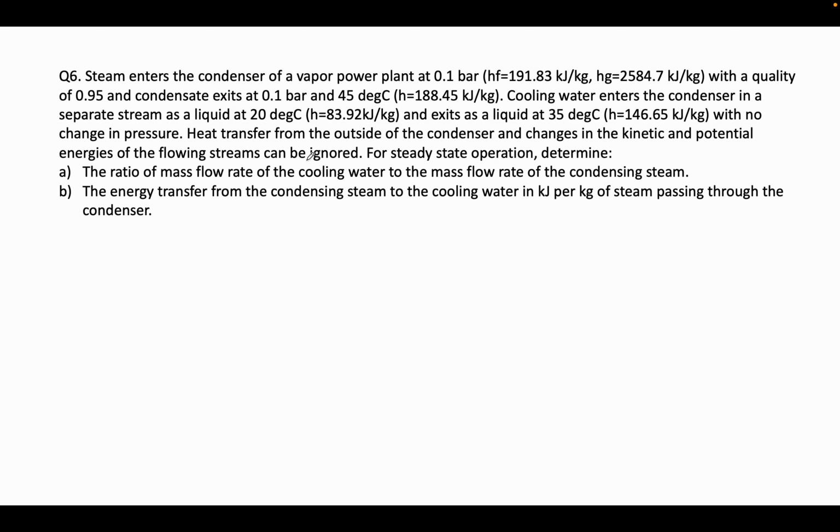Now heat transfer from the outside of the condenser and changes in kinetic and potential energies of the flowing streams can be ignored. For steady state operation, you have to determine the ratio of the mass flow rate of the cooling water to the mass flow rate of the condensing steam, and then you have to determine the energy transfer from the... okay, let us first calculate the first part.